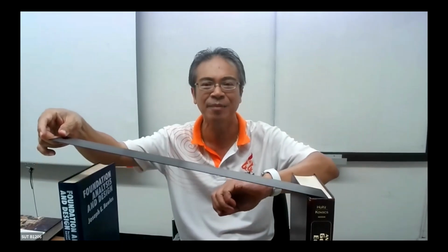If you recall the Muller-Breslau law for the design of this precast concrete beam for the highway bridge, this is a simple beam. Release this one, lift one unit. The influence line diagram of a determinate beam is a straight line like this. You can remember it. The influence line diagram of R sub B is going to be a shape like this. Okay, that's all I would like to tell you about the deflection diagram.